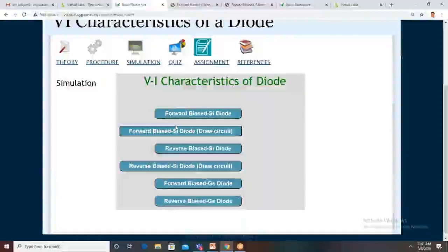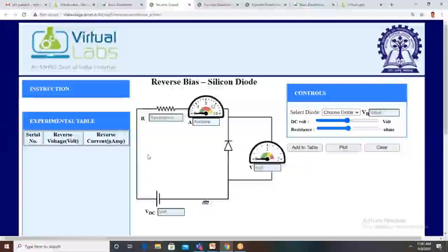So what we did so far, we took this circuit, made the connections and performed the experiment. In the next case, for the reverse biased case, I am taking the ready-made circuit, where the connections are already made available just by selecting the diode. In the reverse biased case, either the diode or the supply voltage is reversed, but not both. If you reverse both, it is again a forward biased diode. Now the diode is reversed, and the connections are already there.